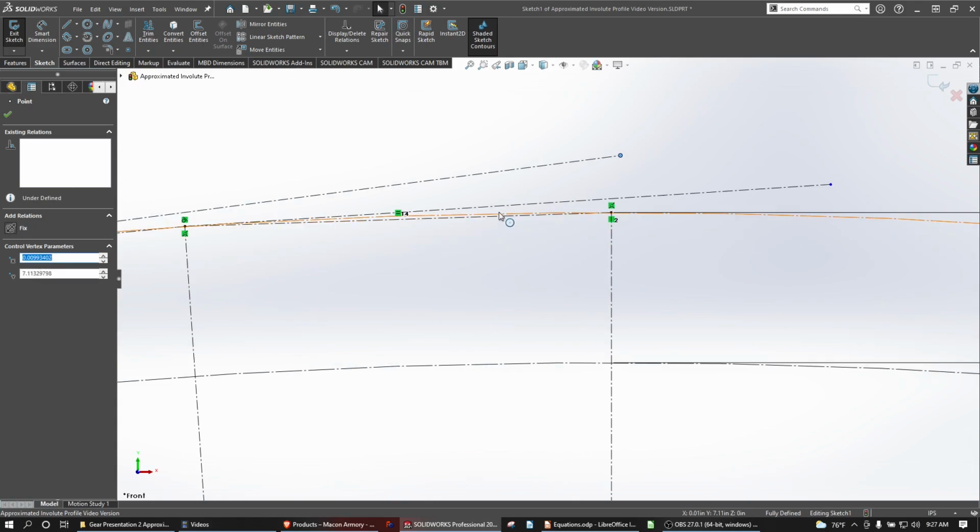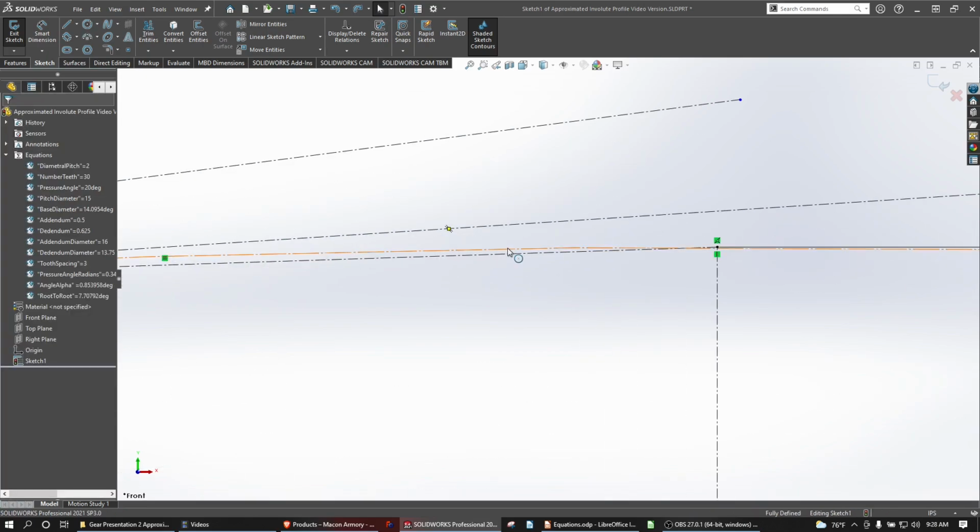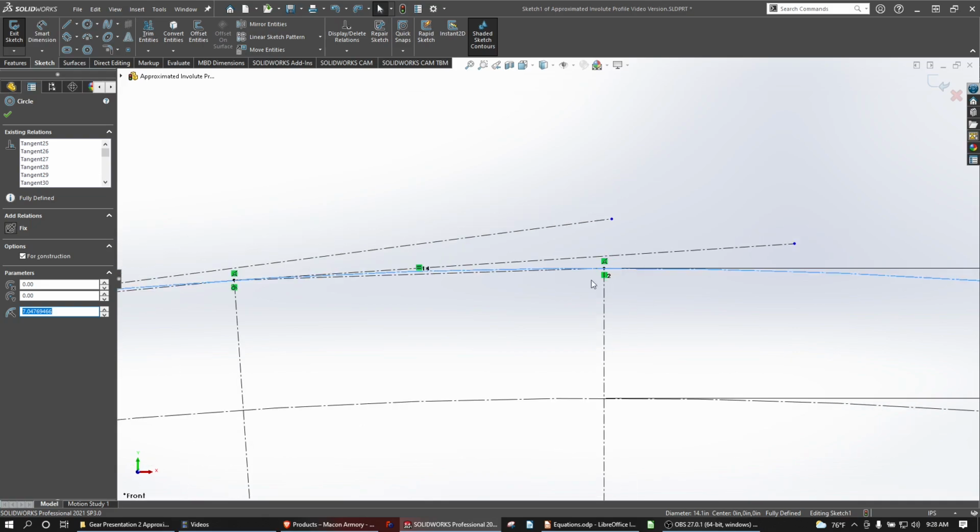And as you can see, our base circle would be the circle that we would unwrap around to create an involute profile. So if we can grab the arc length of an arc from here to here, I believe that we can create certain reference points as an involute profile. So we care about the arc length from here to here.